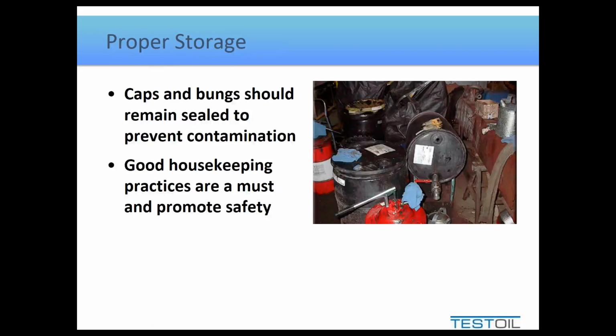When you have your drums in play and they've been opened and you are dispensing from them from your storage area, always make sure you put your caps and bungs back on. Leaving drums open to the atmosphere, even just for the sake of saying that, well, you need to let the drum breathe in air as you dispense fluid, that's going to introduce contamination. So we should employ some good housekeeping practices. We want to keep the system that the oil is going into as clean as possible, so therefore we need to treat the oil that we're storing in as respectful a manner as possible. So we're going to keep everything clean, everything buttoned up tight.